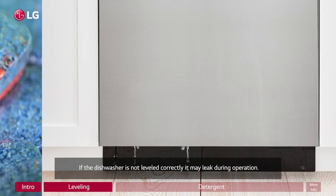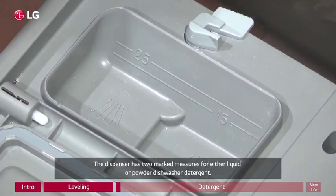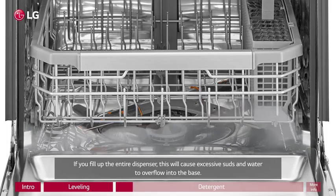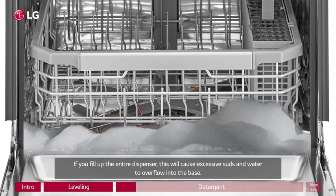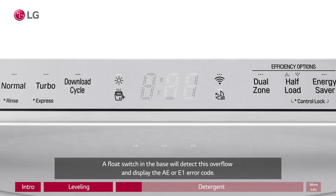Detergent. Now let's talk about detergent. The dispenser has 2 marked measures for either liquid or powder dishwasher detergent. The dispenser cup has compartment labels embossed 25 and 15. If you fill up the entire dispenser, this will cause excessive suds and water to overflow into the base. A float switch in the base will detect this overflow and display the AE or E1 error code.